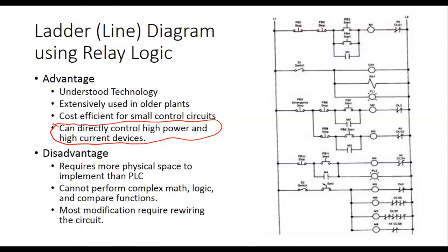So, of course, we had to learn a bunch of symbols. This is not the way it appears; this is the way we wire it. So these are relay contacts. This is a solenoid. This is a light. These are push buttons. These are contacts being controlled by it. Now notice every relay has a name, so they're calling this M1. And every contact controlled by M1 has the same name. And so they brought this over to PLCs also.